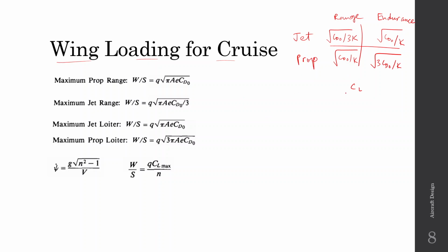So you can use these equations to easily find the wing loading. Ignore this section, this is for the turn rates. So what you do is you write now in cruise condition. In cruise condition, you also know the simple equations, which are lift equal to weight and thrust equal to drag.